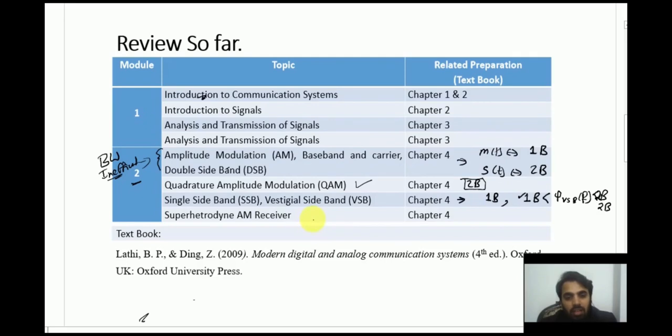And we concluded our last class on the superheterodyne AM receiver. You can also call it the superheterodyne AM/FM receiver. So this whole phenomenon works for AM as well as for FM receivers. So what we do is we obtain the RF signals, and from the RF, radio frequency, we use what you call a filter and a multiplier that puts the spectrum of the station of interest at a specific intermediate frequency, and then we process it and get back our original signals. In terms of the aspects that are remaining in module number 2, there are very few. We will be talking about the aspects of phase lock loop and some other carrier acquisition aspects, and then we'll move on towards module number 3.